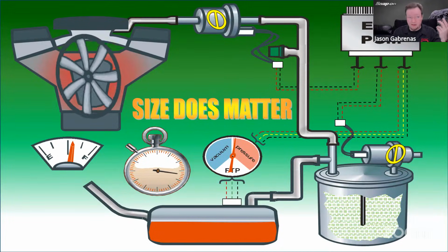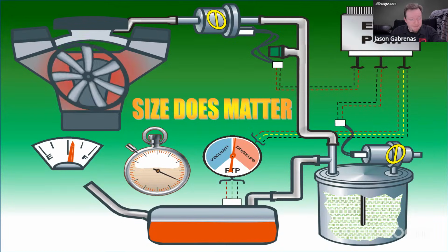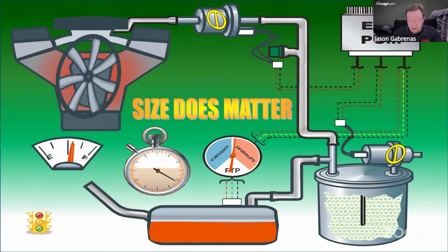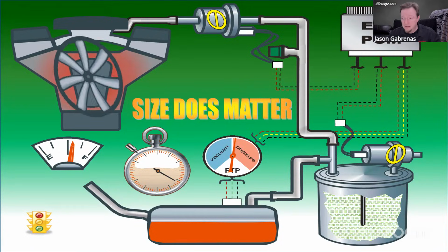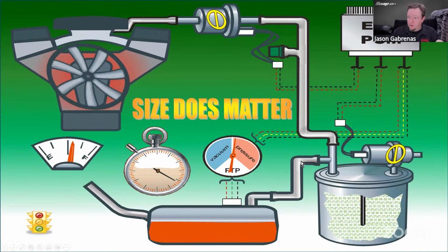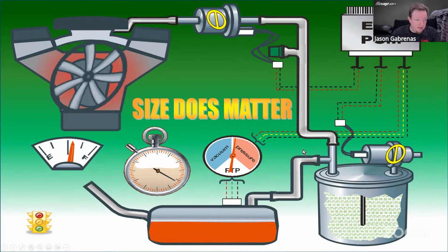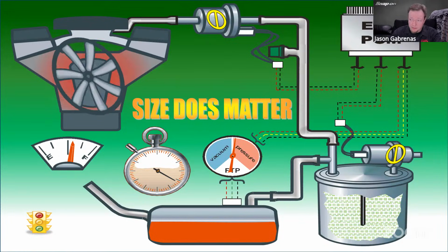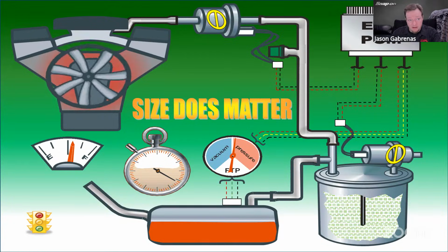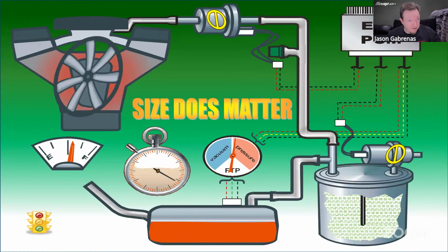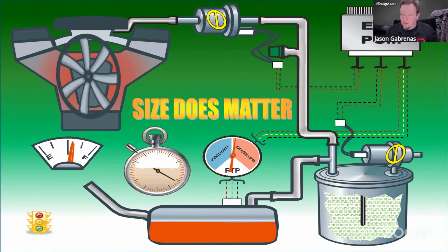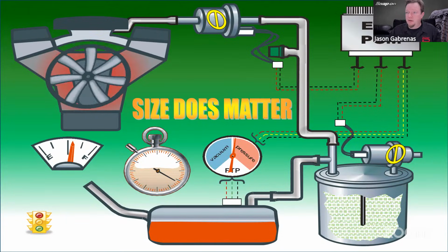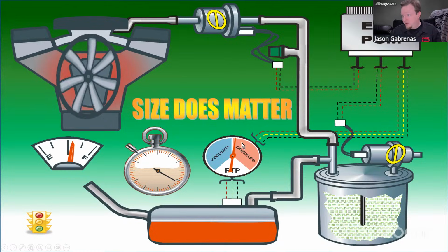So if it's over a certain threshold, depending on the year of the car, it's 40 thousandths pre-2000, 20 thousandths post-2000, and now we have quite a few vehicles out there where it's 10 thousandths of a leak. There's also some vehicles out there like my Subaru that is PZEV. I don't know if you've ever seen that logo before, but PZEV is partial zero emissions vehicle. And the zero part of the emissions in that case is actually the Evap system. So it lets no Evap emissions out into the atmosphere. So I guess it just does a good job of capturing it. Anyways, probably marketing. And this vehicle definitely needs a fan.